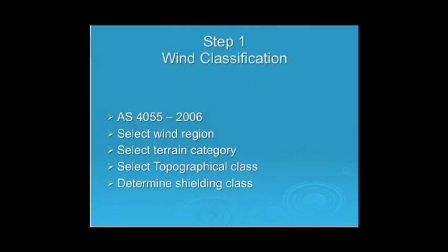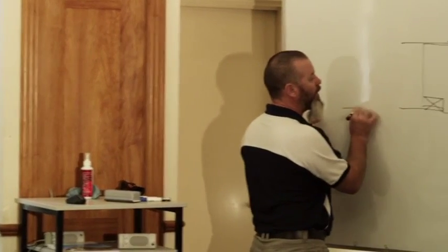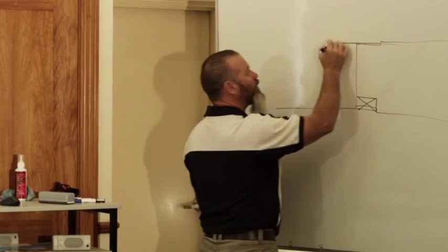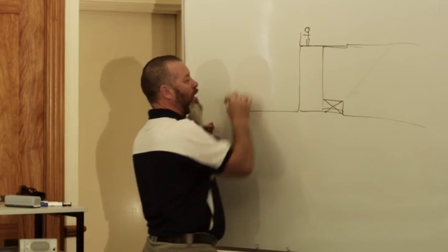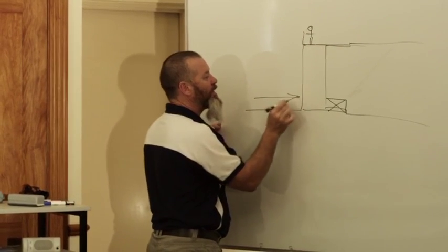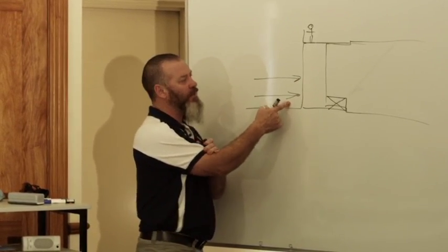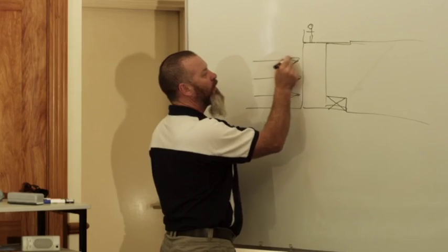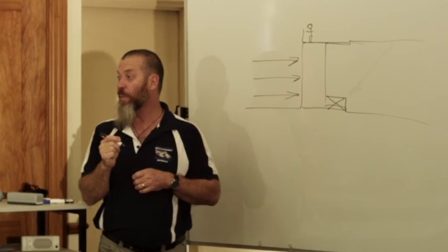But you must have a look out where you look over the coast here somewhere. You always stand at the top of these lookouts and you can feel the wind rushing up underneath your shorts, yeah? Coming up from down low. If you think about this here as being an escarpment, and you're standing up here, and the wind's coming across, if you think about wind arrows hitting there, say you've got a wind pressure here of 10 kilopascals, this is 10 kilopascals, this is 10 kilopascals, so in total, if you were to add them together, that becomes 30 kilopascals.